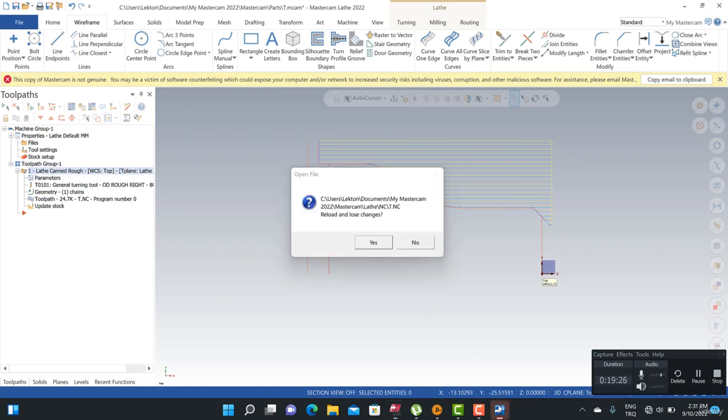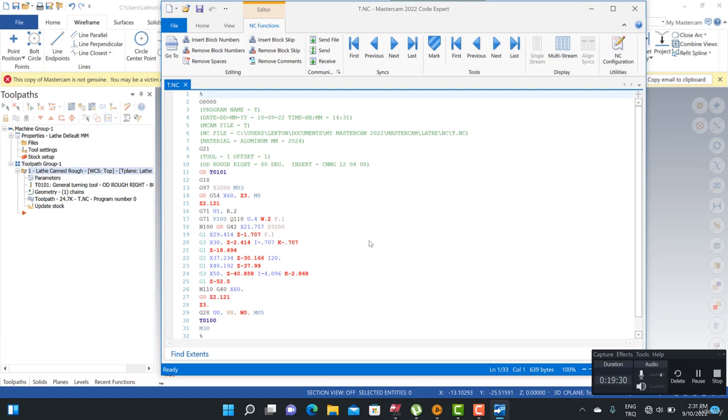It's active right now. Can you see that? Yeah, we can also see some tool radius compensation parameters here. That's one. This is the cancellation of the diameter compensation parameters here. And I also need to see G42 here for compensation for my radius. Okay, yeah, that's it.